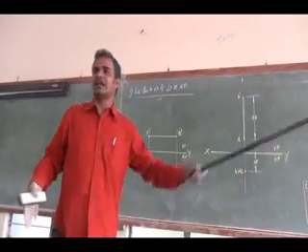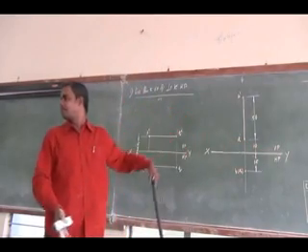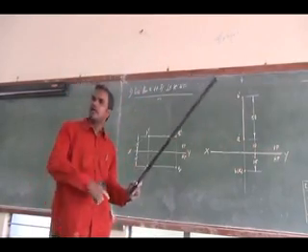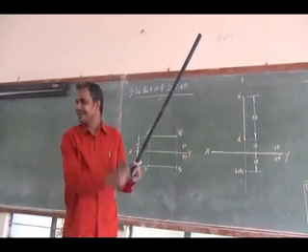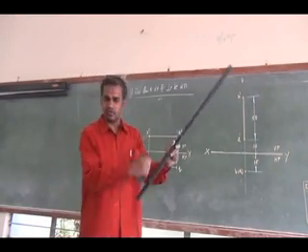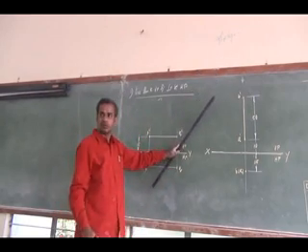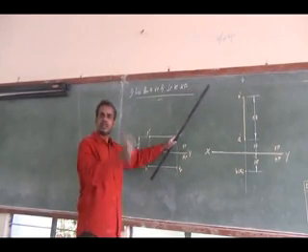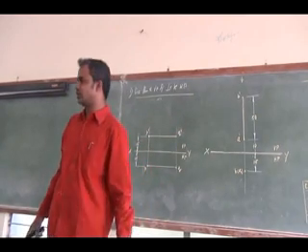So it will be a shorter length of straight line which will be parallel to the reference line. In the front view, I will obtain a true length with an inclination of 30 degree. That inclination is nothing but a true inclination. The line's inclination, what is given in the problem, it is 30 degree incline. So in the front view, the same 30 degree I will obtain. That is called true inclination.